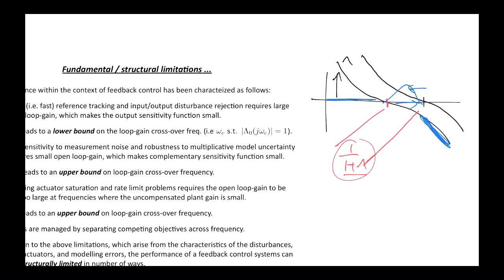Okay, and this is the transfer function from the reference to the error. It's the transfer function from an output disturbance to the output signal that gets measured and fed back to the control system. So if we know that the reference has a lot of energy at low frequencies, we want to make sure that that's small at low frequencies, and that's achieved by making lambda large.